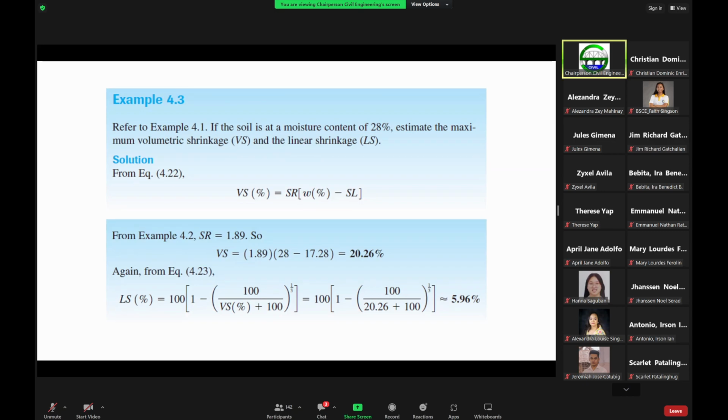So that's the number of tests. Then, for example, in one site we have about 10 boreholes at about 30-meter depths. That's 10 boreholes times 20 samples per borehole. So for that project, you have to do all these tests 200 times.